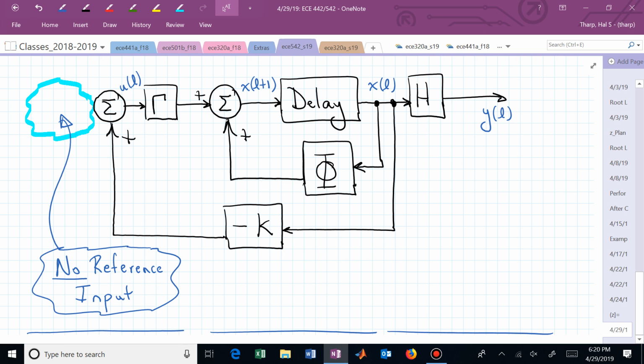No. We have no reference input with just full state feedback. We can only influence the dynamic behavior. We can't really say, oh, I want you to go to 4, and it dutifully goes to 4. No, we can't do that. We can just sort of watch the system behave the way we want it to behave, which is maybe to have modes at 0.8 plus and minus j0.2.